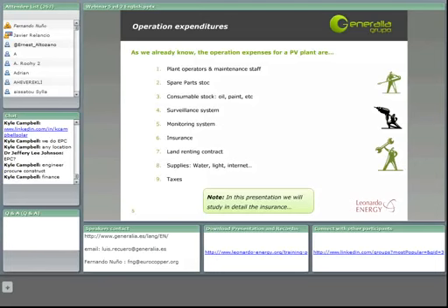Obviously, if we are talking about a roof, we have to check that the building will last 25 years, and that no other building will be set close to ours, because we have to pay attention that any building that will be constructed in the future may cause new shadows in our installation. We also have to know that the urban terrain is much more expensive than the terrain in rural areas when selecting the land that we want to contract.